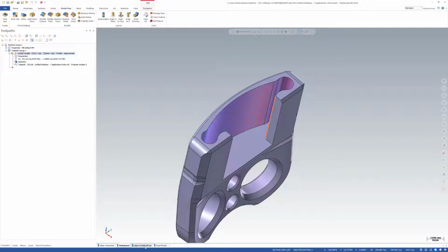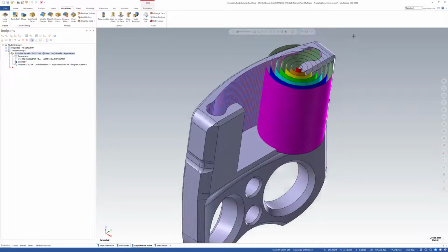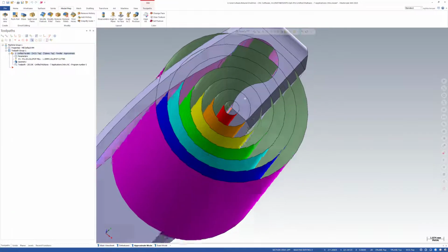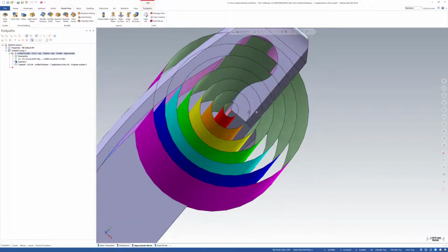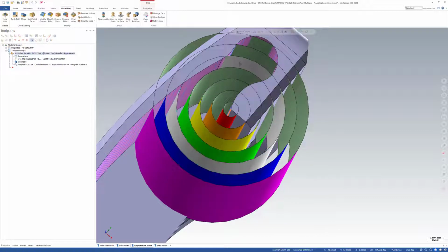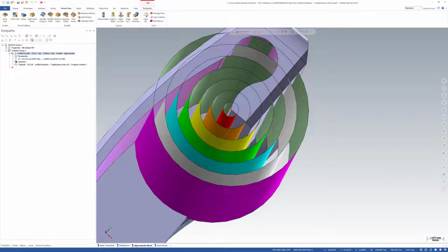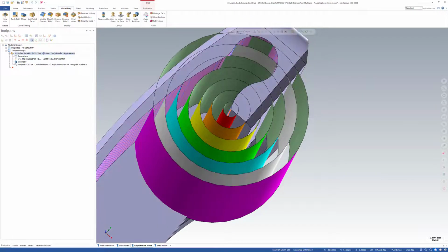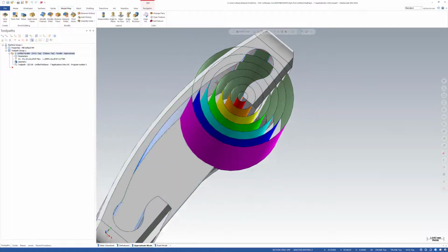The way that approximate mode generates toolpaths is purely based on offsets. So we're basically creating this offset. These cylinders are offset by our stepover. Every time this offset intersects with our drive surface, we get a machining pass. So as we get out here, we intersect over here and over here before this next one. So we get a pass there and a pass there before our next pass on this normal face.